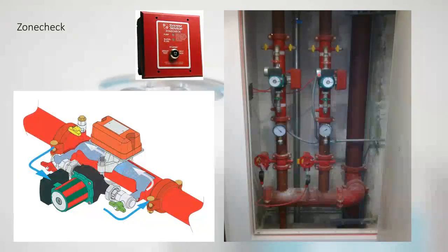It looks something like this. Okay, so it just circulates the water around the flow switch, that paddle moves, you get a touch of the plates, you get the alarm. Okay?